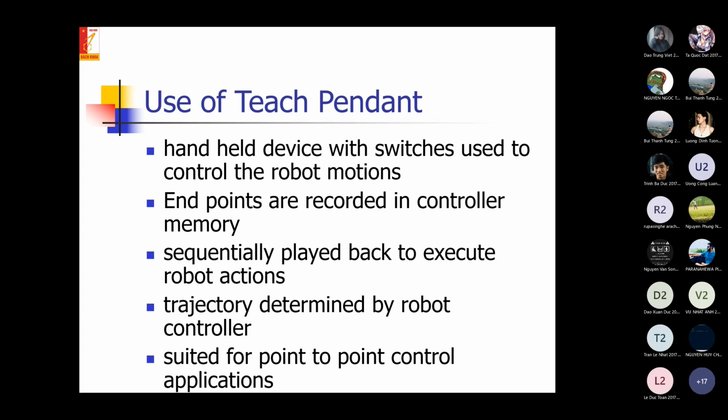And this pendant is linked to the controller or the CPU of the robot. So the endpoints are recorded in the controller's memory, and sequentially played back to execute the robot's action.